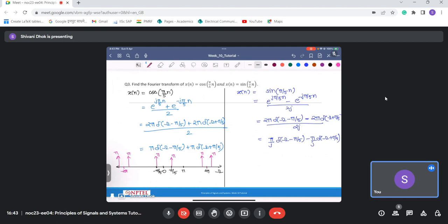So this is basically a periodic function that we are having here, and this periodicity exists for the DTFTs of all the signals that we have. Now, one more thing that we need to note in this example is that x[n], cos(pi/5 n) and sin(pi/5 n), are both periodic signals, and the tool that we have studied for frequency analysis of periodic signals is the discrete time Fourier series.